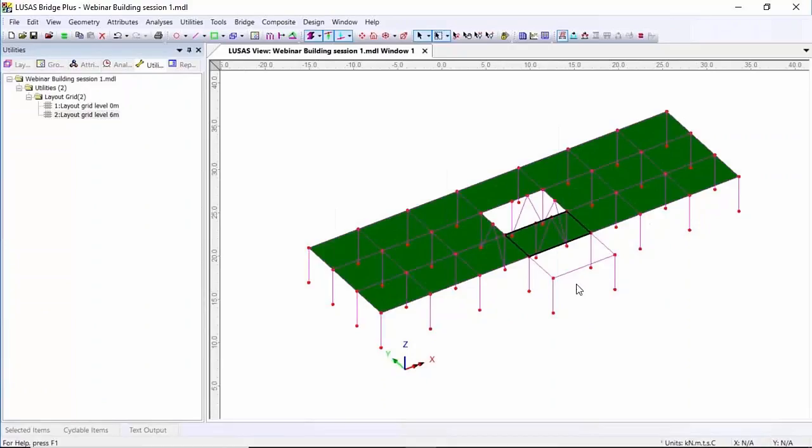Okay, now at the front of the building here, I need to create a couple of extra lines. So I'm going to take this point and this point, create a line. This point and this point, create a line. And finally, I can turn these into surfaces. So select these 3 lines, hit the surface button. Select these lines, hit the surface button. And finally, these lines and hit the surface button.